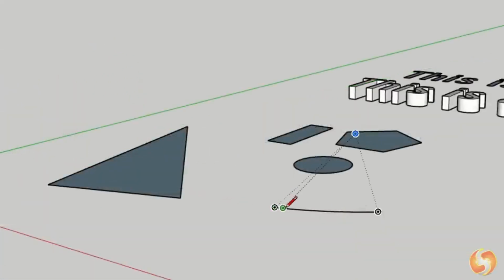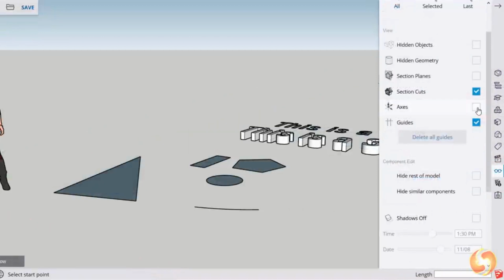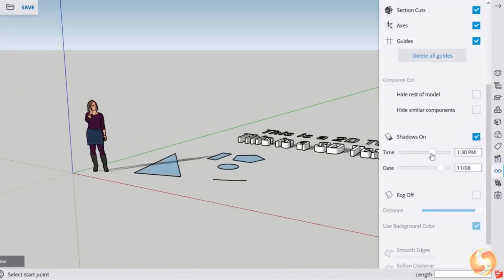Besides these colors, you also get snappings to the most important object key points, such as colored circles for vertices and nodes, squares for points on sides, and rhombuses for points on faces and filled areas. Also, dotted guidelines may appear, indicating perpendicular directions, intersections, and extensions over objects, sides, or axes. From the display panel, you can manage the aids to use, and also apply visual effects on the preview, such as shadow and fog.